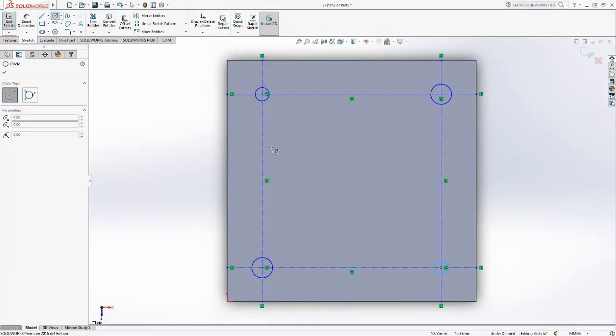Back to SolidWorks. We go down this line, we trace down till we come to this center point, which lights up orange. We drag across, and now you notice that we have this dashed line that comes in. Now we'll go up to this top line, find that same orange point and drag down, and now we have a vertical. As we come close to the vertical and horizontal, we get two dashed lines, which is great.